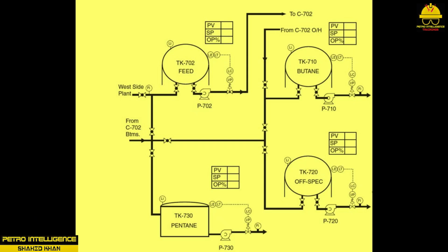Feed system. A collection of product storage tanks is often referred to as a tank farm. The tank farm has a complex system of piping, valves, and pumps that allow the technician to line up the various tanks in a number of arrangements. The tank farm in this example has 4 storage tanks assigned to the debutanizer distillation column, as shown in the picture.